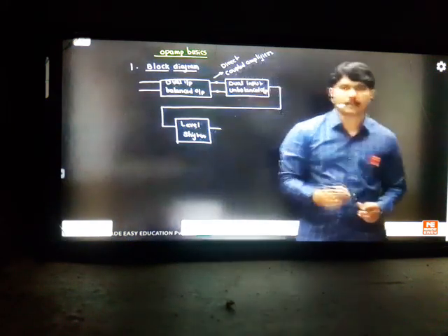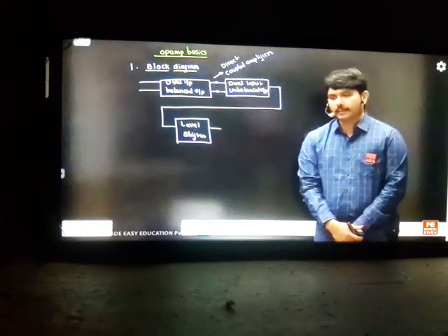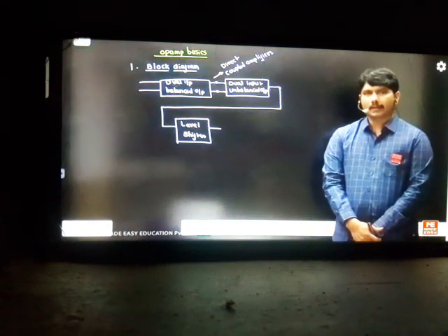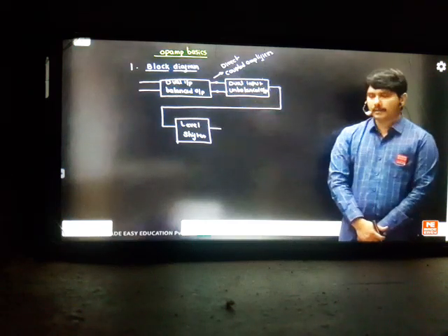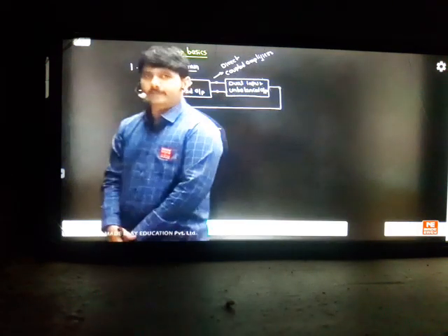In integrated electronics, we are not using RC coupling. We are using direct coupling here, where capacitors are not taken into account. In the previous class, when I was teaching voltage amplifier analysis, we used RC coupling. Here we are using just direct contact, so they are called direct coupled amplifiers. In direct coupled amplifiers, there will be no coupling capacitors.